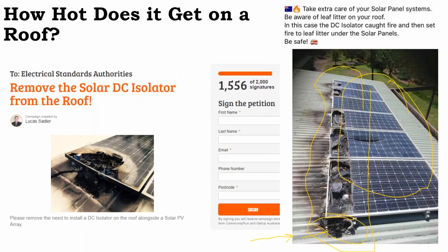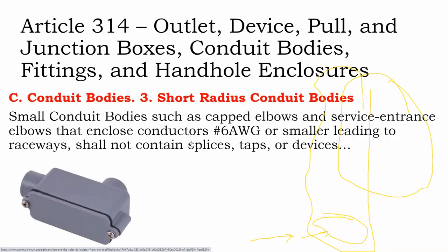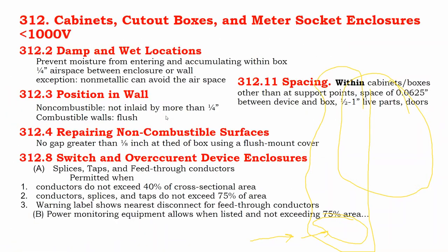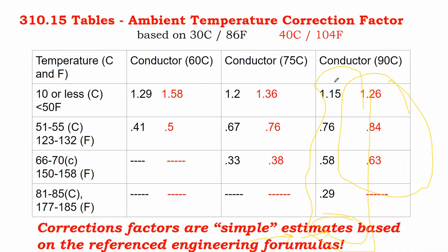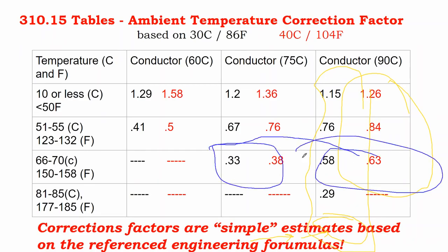And so if you've been doing all of your temperature calculations assuming a higher temperature rated device, and you go and swap it out with a lower temperature rated device, then we saw with those temperature correction factors that the temperature derating for lower temperature devices, we saw that when you use a lower temperature device, the derate factor is substantially larger, 70% instead of 40%.